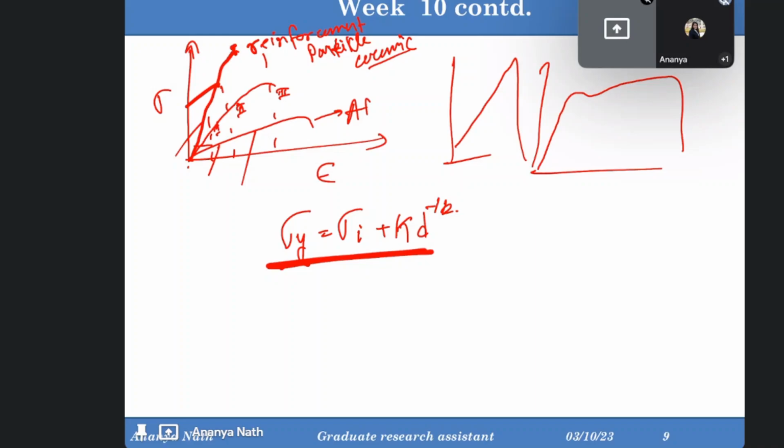So the dislocation will play an important role, because if there is a lot of dislocation in the interface, then it may happen that the dislocation will glide and the interface will be less bonded with the matrix, and the reinforcement particle also will glide with the dislocation, and there will be no strengthening in the interface. So this is why the dislocation density is also important.